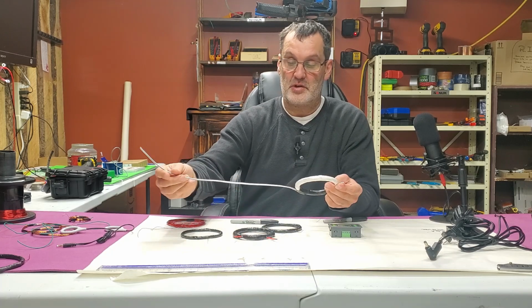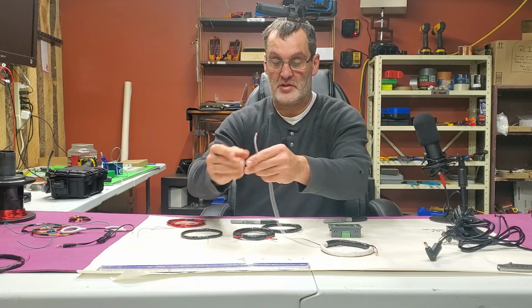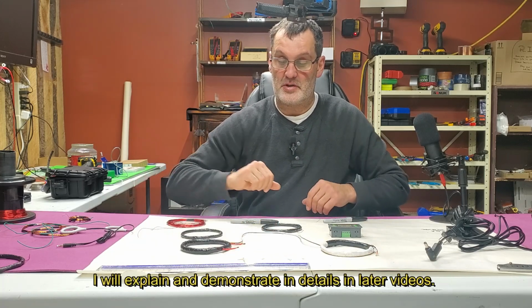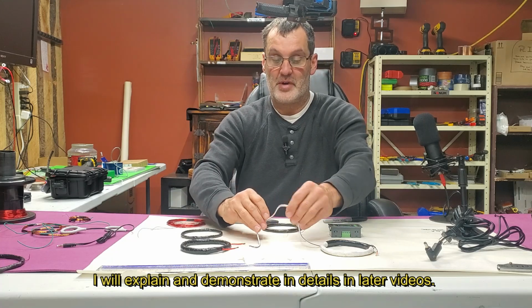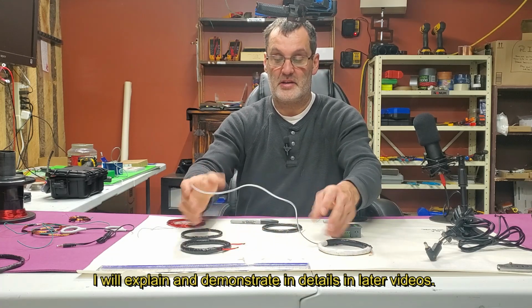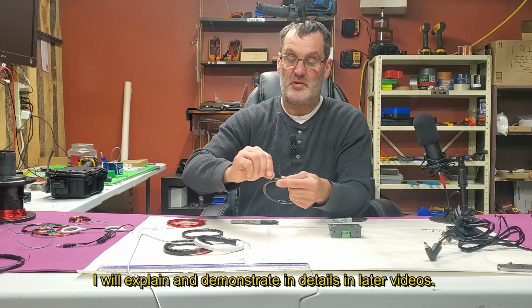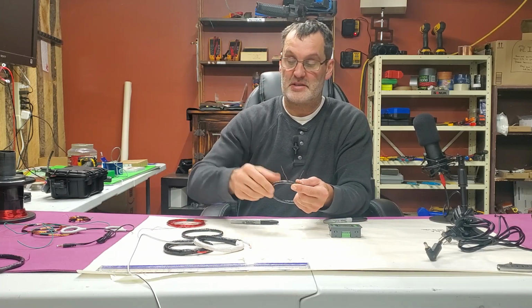So when you go from one coil to the next, you have a long connection between coils, so when you fold your mat back and forth, you don't break this wire. Magnet wire does not like to be bent over and over again at the same place. It just breaks.